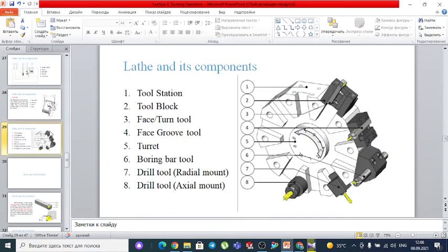And the tool changer, or we can call it the turret. Here you see there are places for the tools, and several tools you see here for the turning operation. A drilling tool, here also drilling. I think this one is for threading, and this, you see, is for grooving, or you can use it for cutoff. This is for facing and rough operation. You can use this tool for roughing and finishing operations. So this rotates.